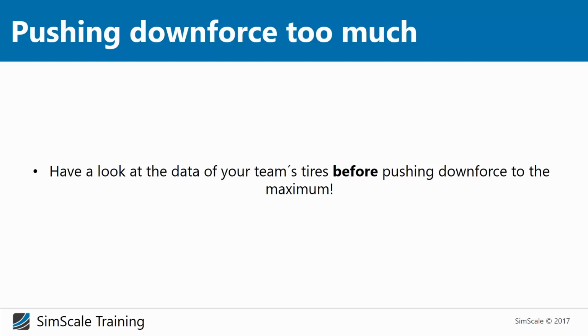But if you have too much downforce, the front tires can get into this saturation area and they will just collapse, and they won't transfer any more side forces. Then you will have a very understeering car, and the tires will just rub on the street, and your tires will get broken very shortly. So make sure that you don't get into this saturation area. That is a very, very important point.